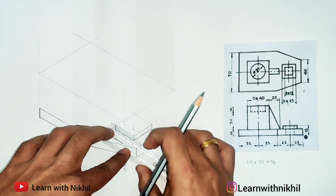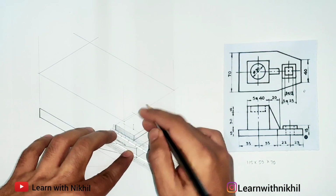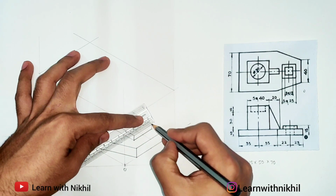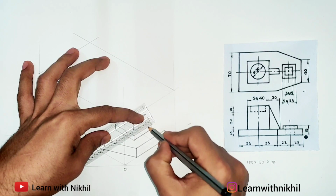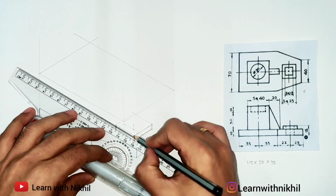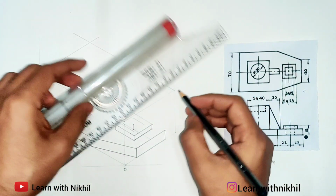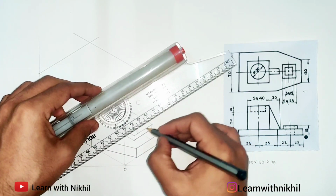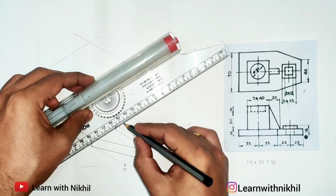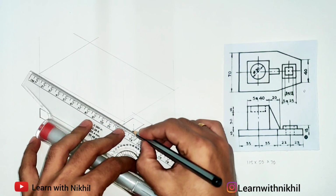So it is given. So directly you can mark here 15 millimeter from the center. So on this side and on this side, so this distance is 15 millimeter, and you will draw parallel lines through here, and the center intersection will be a square. So this is how we got the square. So this is the inner square, its side is 15 millimeter.